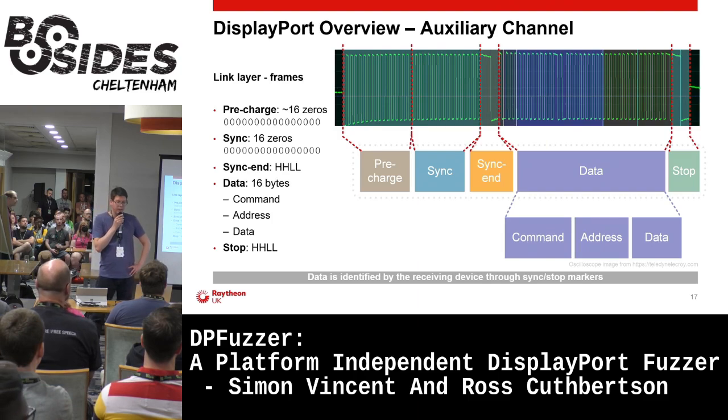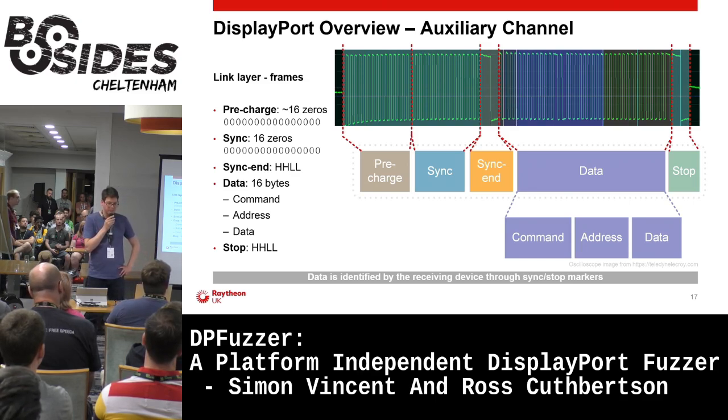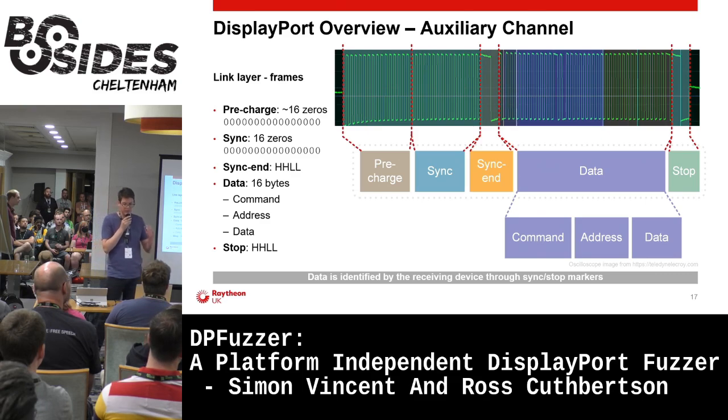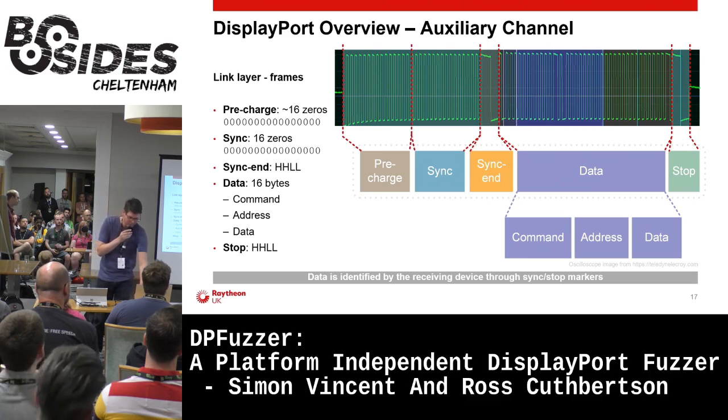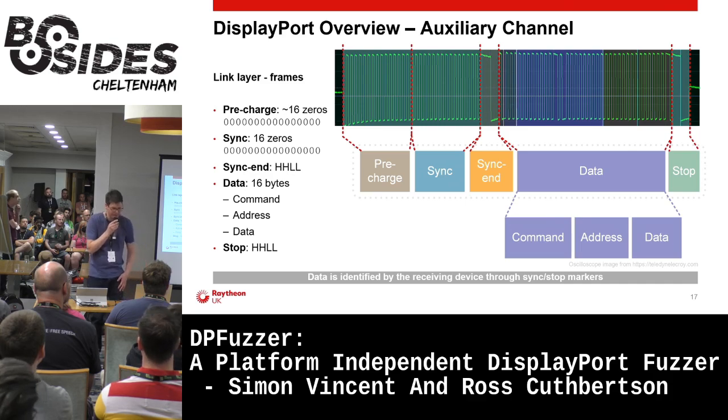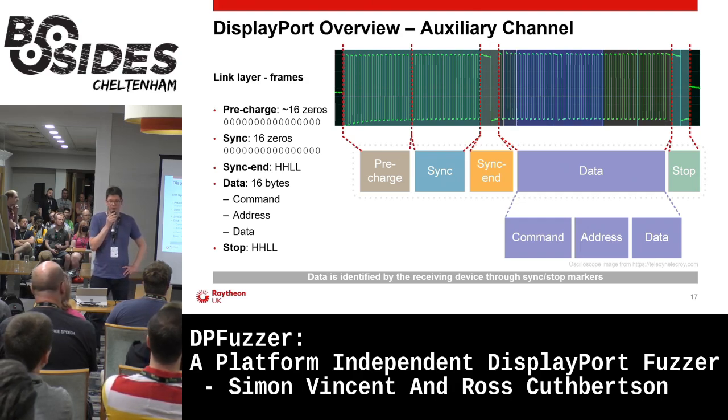At the link layer, we need to understand how the data is framed. This helps the receiver identify when the message is on the channel. So the channel is idle to begin with, and then the start of the message is identified with zeros, and then there are 2 markers. So you've got the first marker and the second marker, and these identify the start and the end of the data. As mentioned earlier, these markers don't conform to Manchester encoding, therefore the data section can be clearly identified.